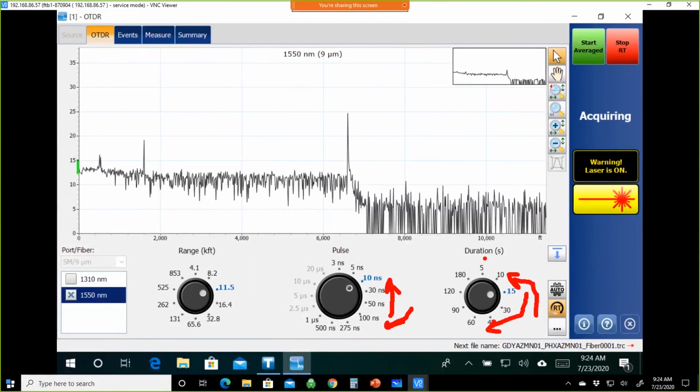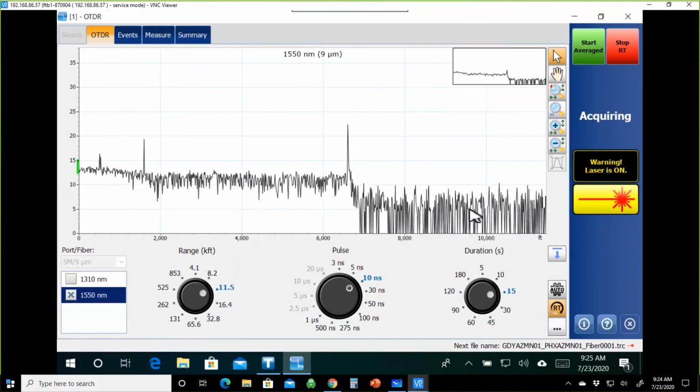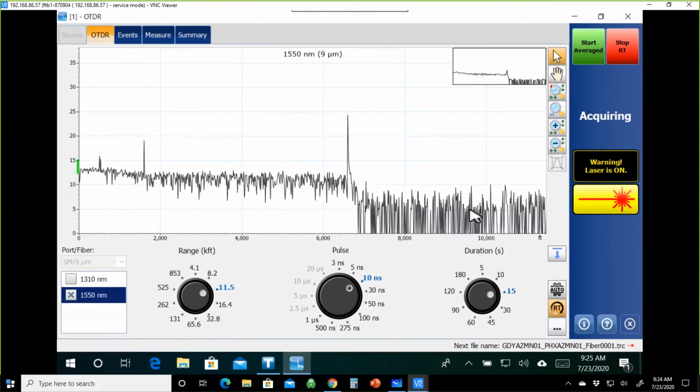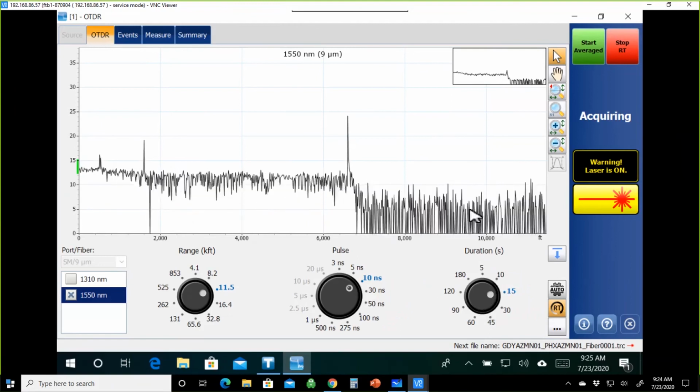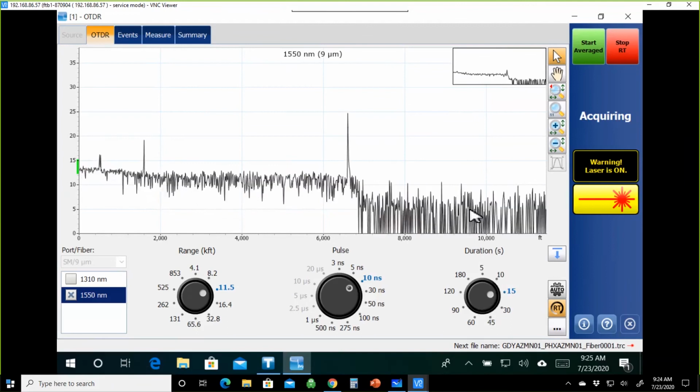If I'm testing an 864, I want an 864 to be as quick as possible. In fact, right now, a good splicer can do an 864 splice in about 7 hours. An 864 butt splice ribbon in about 7 hours with a good machine and a good setup.